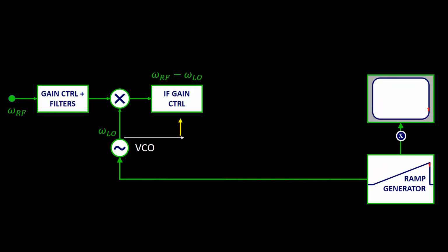And if we apply a sinusoid, we will see something like this. We can now keep the voltage at y-axis and apply another triangular pulse to the x-axis. Doing this, we will repeat the waveform in the display and therefore obtain a stable visualization of our signal. Good, we have built an oscilloscope, but this was not our objective. We want to convert the x-axis into frequency. And this is the hat trick we need.